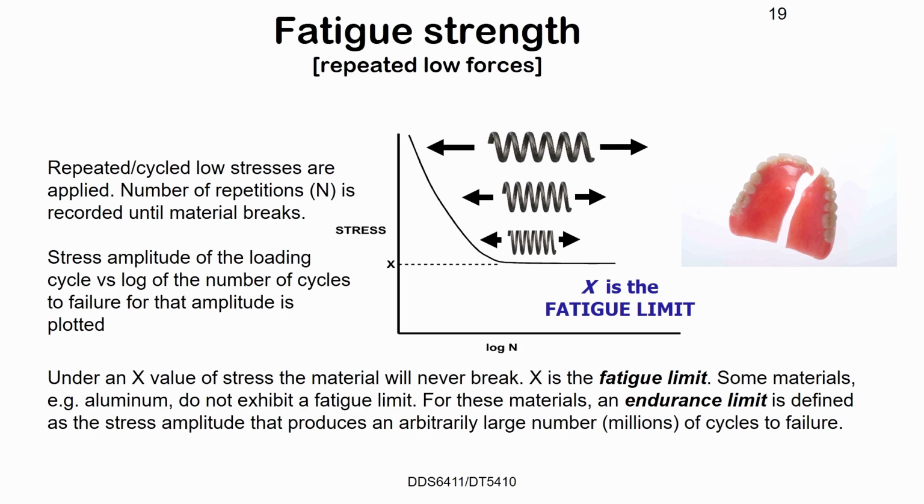It's called the endurance limit, and they are usually in the millions. So for example, I want a restoration that will last 10 years. You estimate the number of cycles of chewing that your patients would do. That would determine the number of cycles required to fail it. And then you back calculate and determine what sort of materials you will need.